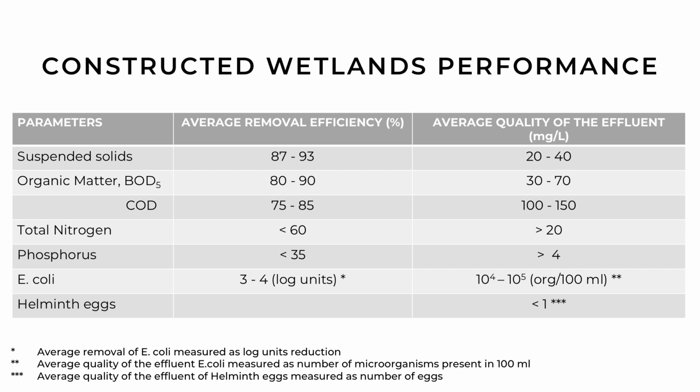Constructed wetlands offer great efficiency for the removal of suspended solids and organic matter, while the nutrients such as nitrogen and phosphorus are maintained. However, constructed wetlands alone might not be sufficient to achieve the required quality concentrations of E. coli to protect farmers' and consumers' health.